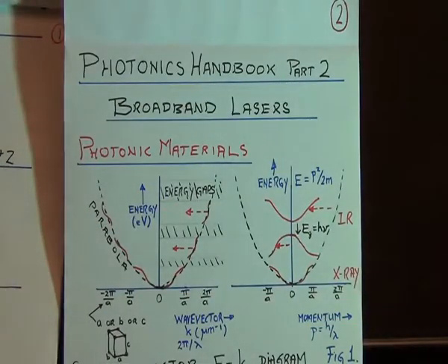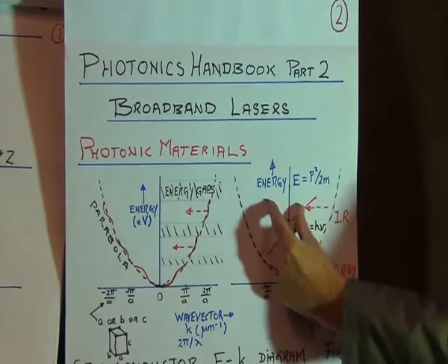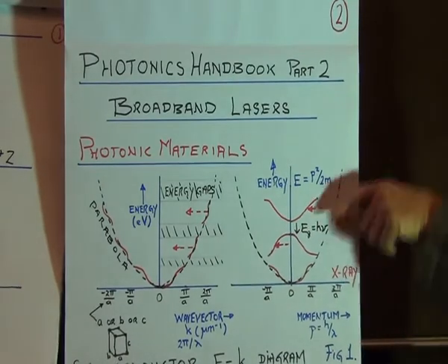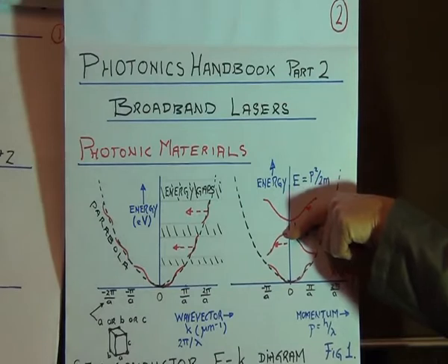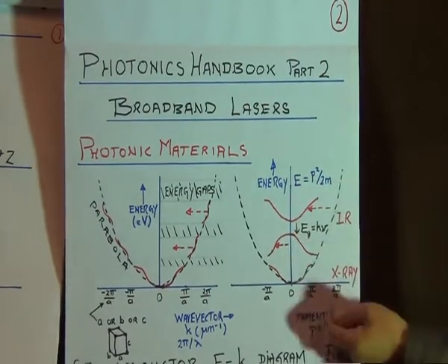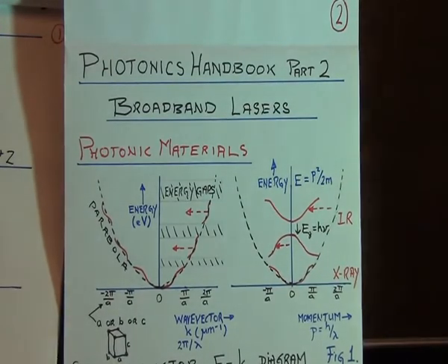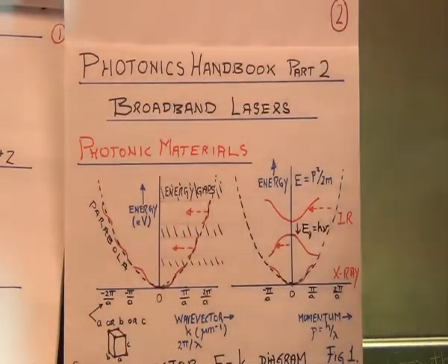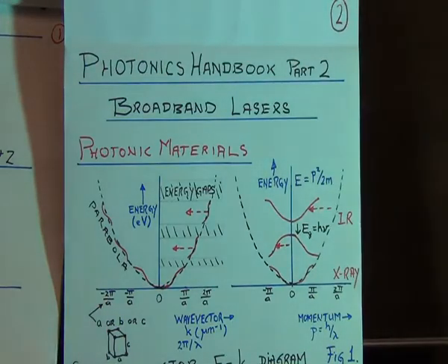However, you do the same now for silicon, and you'll find that this basin is sideways translated, and the dip is up here. That means the electron has to make a diagonal transition to reach the valence band. Diagonally means there's a change in momentum. You must conserve momentum, so there must be a third particle present to help conserve momentum.